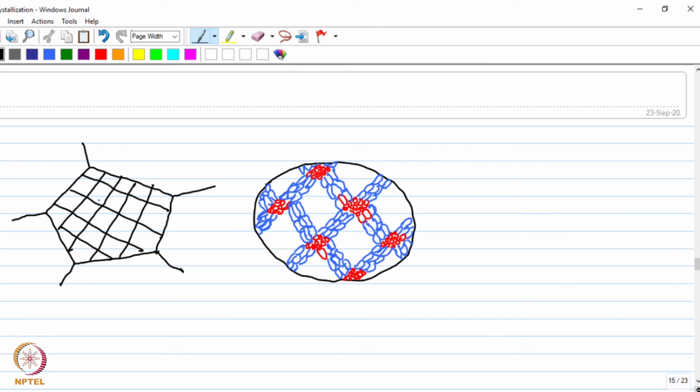So let us say if you talk about any two adjacent domains such as A and B, these microshear bands are now separating these domains. So now if you just magnify this and look at these two domains, as the deformation is increased, the misorientation across the domains will increase.